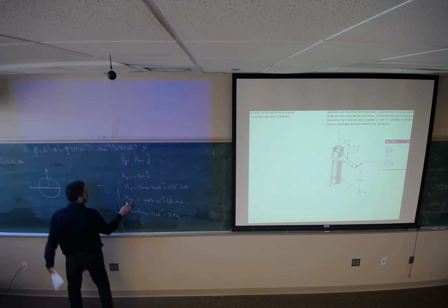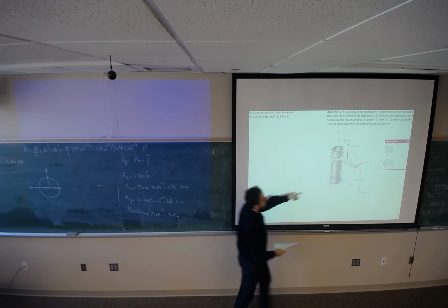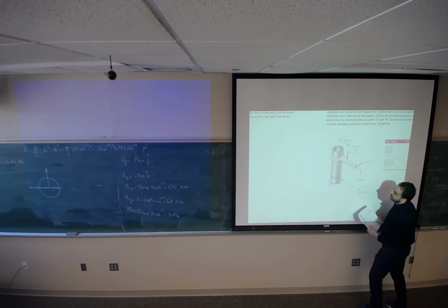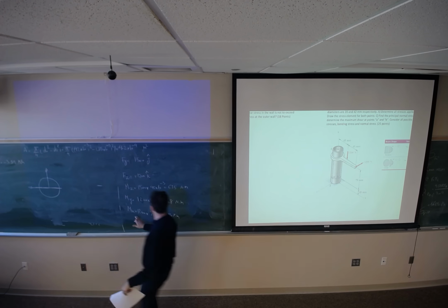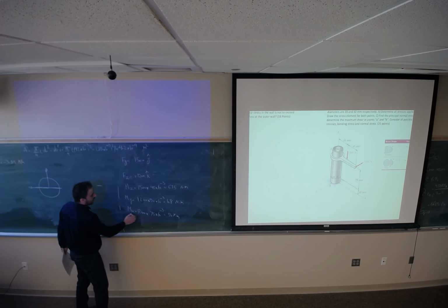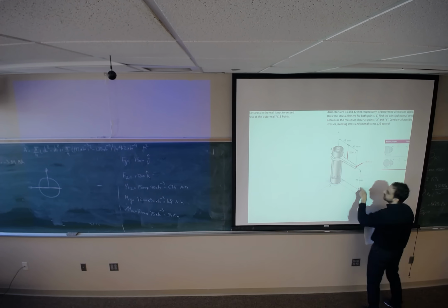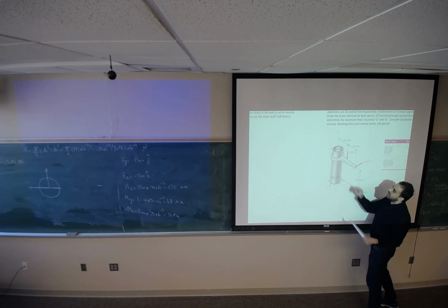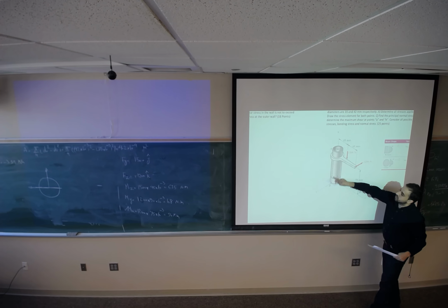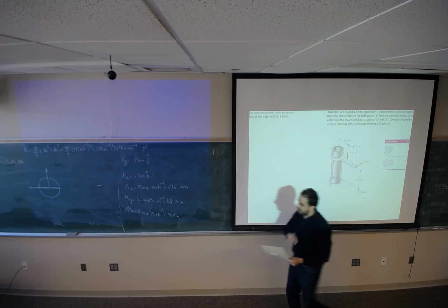But MY, it's making rotation about MX. MX is making rotation about x-axis. So the neutral axis is gonna be this. So point A is gonna see the maximum normal stress.